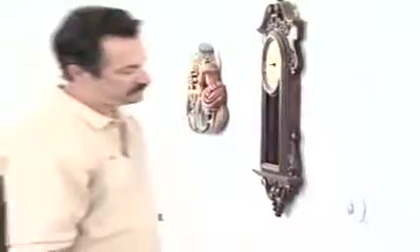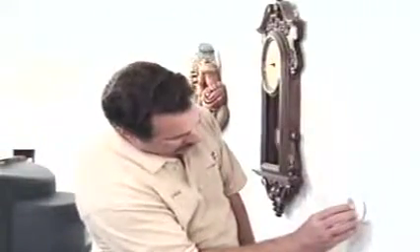You don't have any heat in the building? Well, just in the classroom area particularly. The rest of the building is fine. Verifying the complaint means making sure you know what the customer's complaint is. So it's just a classroom that has the problem. Right. There's some warm air coming in. When I turn the fan to the on position, it works. But then when I turned it to the auto position and turned the thermostat to cool, then it wouldn't work. Make sure the unit is doing what the customer says it is doing. You should be able to recreate the conditions described by the customer.